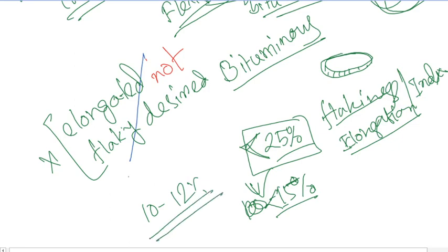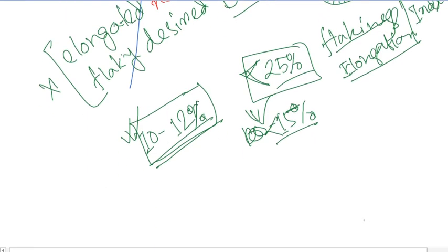will be conducting the test using your lab, or you will be sending this to an IoT lab or wet lab, wherever directed from the authority. Then after the test, if you find that a satisfactory result has been obtained within a tolerance range, then you will finally accept this sample for the construction of the pavement. So both prior to the construction, during construction and post construction period, we need to conduct all these tests of aggregates.